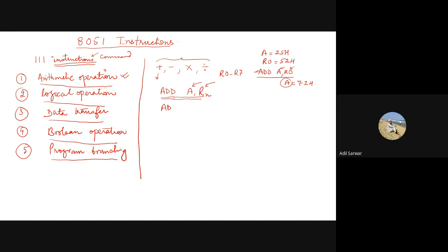Now we can also use ADD in immediate addressing mode. I had told you that there are various addressing modes in 8051, and I showed examples with the help of the MOV instruction. The MOV instruction comes under the data transfer instruction set, and I will talk about it later. But all the modes of operation that I talked about for MOV are actually valid for many other operations also, for example, the ADD operation. We can have all modes of operation possible in ADD also.